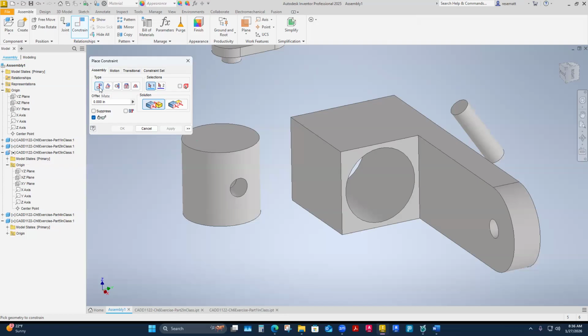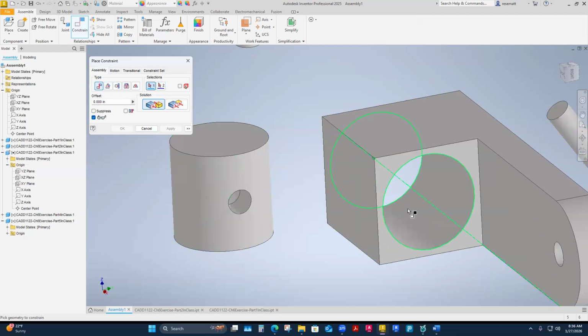I think that's the only thing I'm going to use. I think I use one angular constraint here, but so here it is. There's a lot of different things a mate constraint can be, but if I choose this mate, it's already like select one. So I'm going to say, well, I want to put this piston in this hole here.